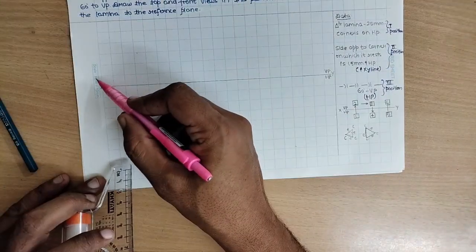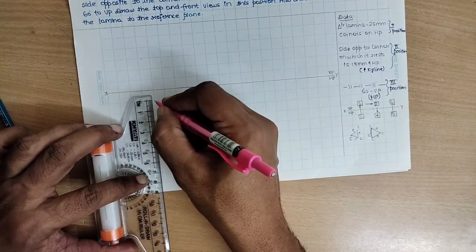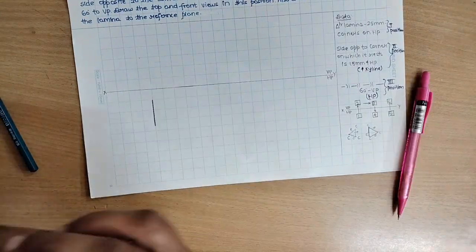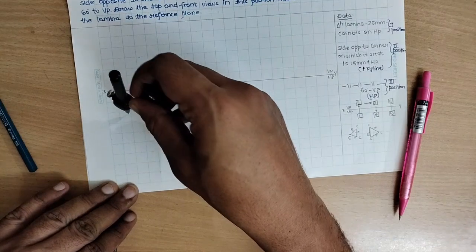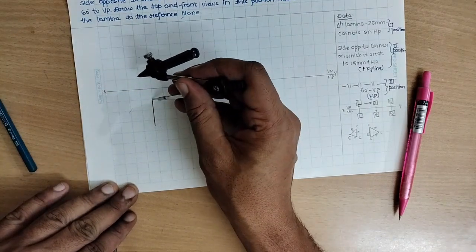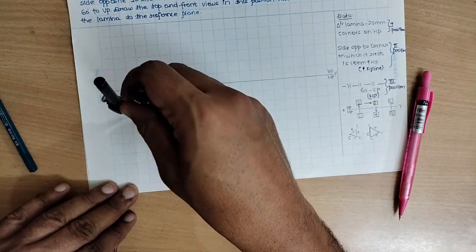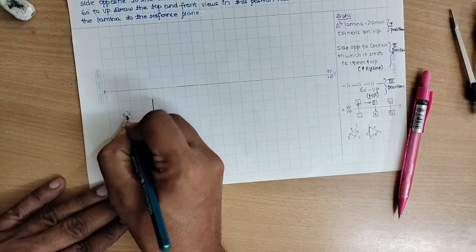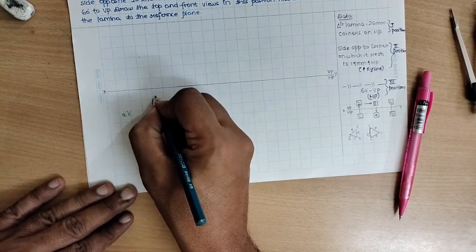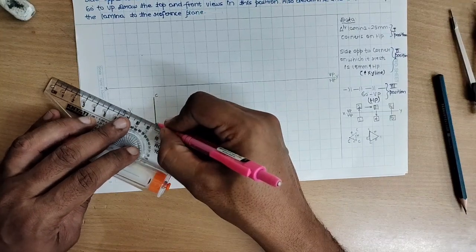The grid sheet says this 1 unit is equal to 10 mm. Let us construct 25 mm, that is 2.5 grid. Make use of compass. This point as the center, take this distance, that is 25 mm. Cut an arc and the other point as the center, cut one more arc so that the two arcs will intersect at a point to get a new point. Call this point as the point A, this is the point B and the point C. Since this is the object, increase the thickness of the object line.